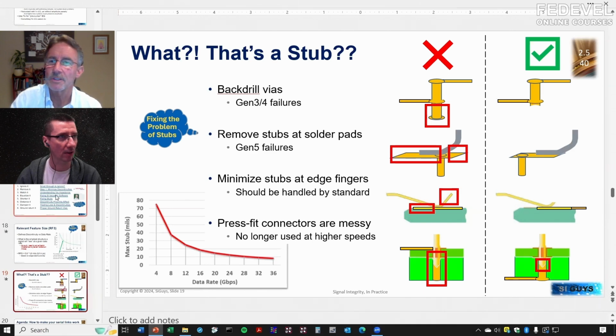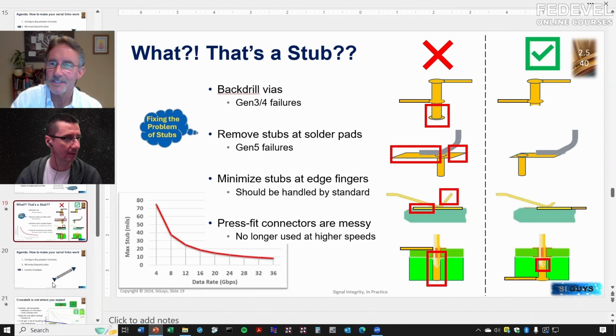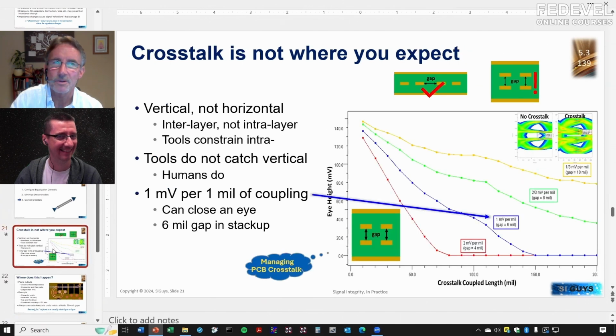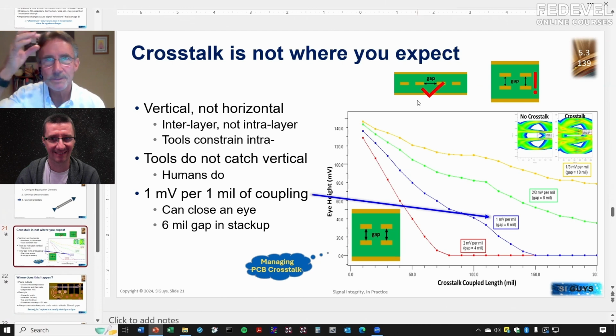Okay, and then next was there crosstalk, if I remember right. Yes, yes, yes. Okay, right. So here's the issue. Now, it's not that you can't have crosstalk in this kind of scenario, right? But that's what everyone worries about, and that's what the design tools handle. So in your layout tool, you probably set some sort of parallelism rule or some sort of gap number, right? They call it different things in different tools. What do you know it as? The gap distance or clearance. Clearance.